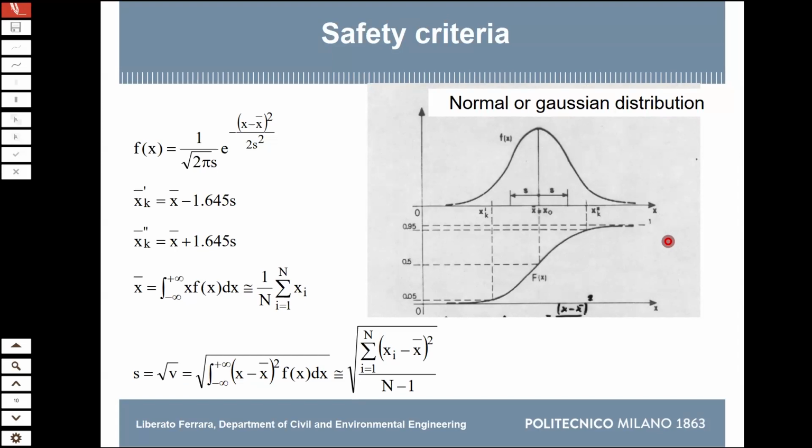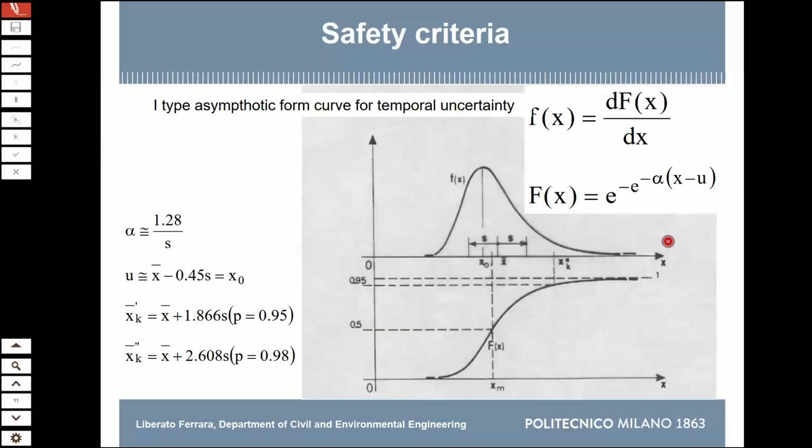Well, for example, this model here is used to deal with tolerances. You prescribe a beam to be 300 by 400, you have to expect some tolerances. And from surveys made on the job sites, it has been shown that these tolerances are very well fitted by the normal or Gaussian distribution. There is another distribution, which is very well applied to the strength of materials, especially strength of concrete, which is the log normal distribution.